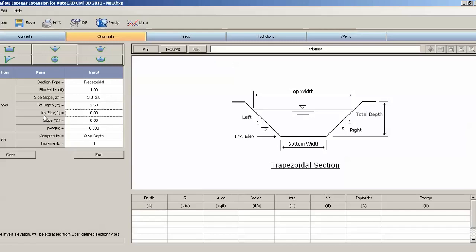And the initial elevation here is the first reading. If you go on site, we have to specify the first reading in the level, which is the first elevation. You have to assume it here because this is measured in the field. We have to calculate that in the field, or you can use GIS to get the contour lines, and by finding the contour lines we can estimate which elevation you have.